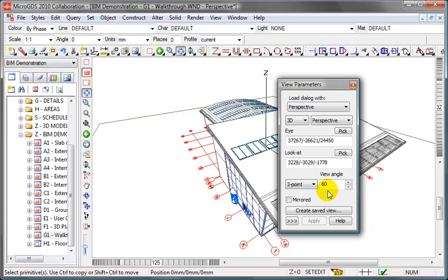The view angle, what is called the field of view in the tools that we've been working with, is set here as well, and 60 degrees is pretty much the natural field of view for an eye, but you can widen it or narrow it as you choose. So you just need to be aware that you're introducing a certain amount of distortion into the perspective when you do that, and you can actually be conveying an incorrect